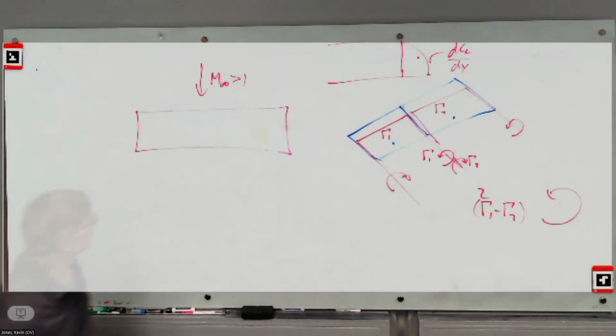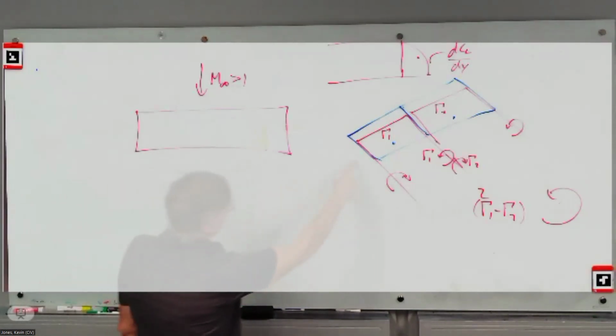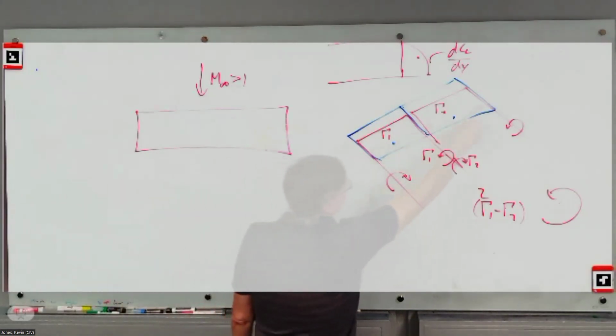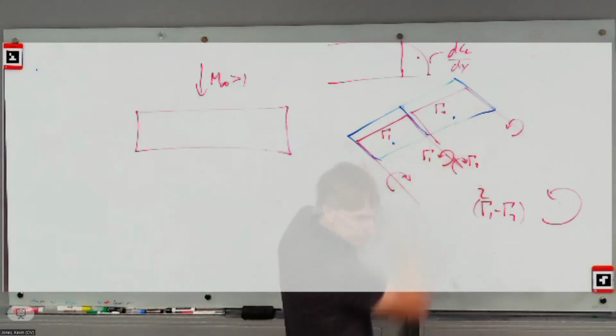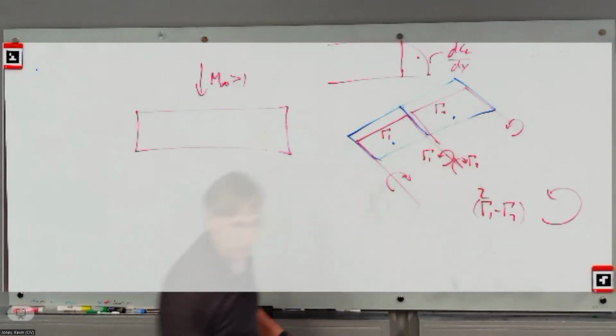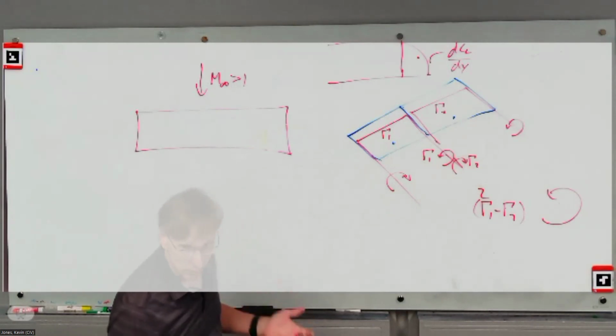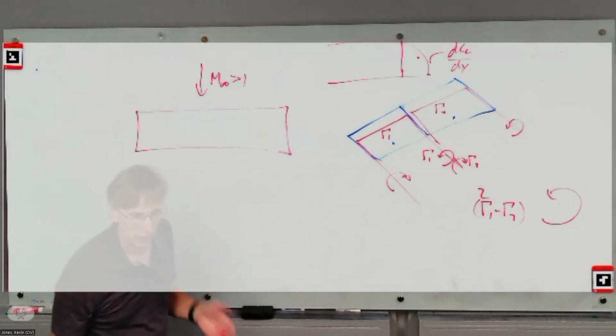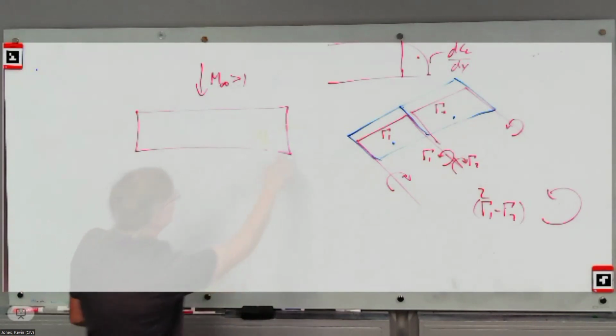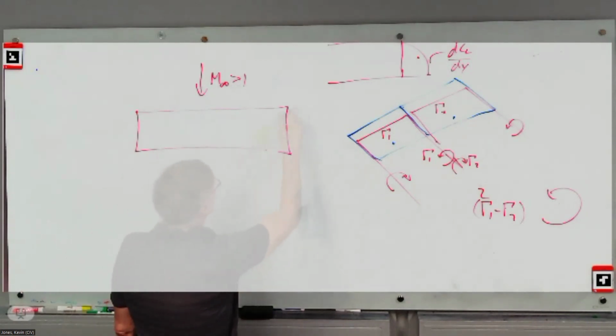You can't. The reason we got this is because the effect of that wingtip in subsonic flow reaches everything. It reaches the entire span. But in supersonic flow, disturbances are contained, right? If this is my wingtip, this is the first bit of noise at that wingtip, it's contained inside this cone, right?